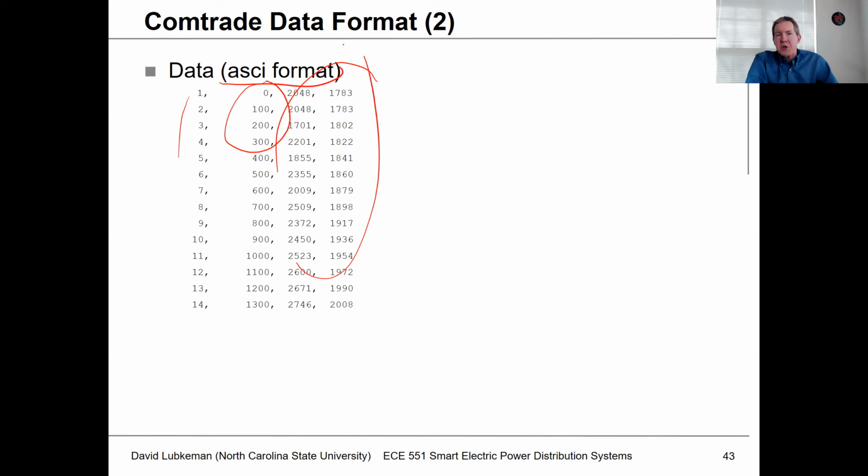And if you have a Comtrade file, there are Comtrade file viewers. Let's suppose you had a Schweitzer relay and you have an oscillographic waveform in a format that's native to the Schweitzer. You could view that with the Schweitzer waveform viewing tool, but if you wanted to give that to somebody else, you can convert that to Comtrade. And then a lot of people would have the ability of actually viewing that file.